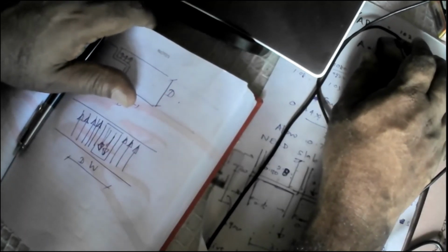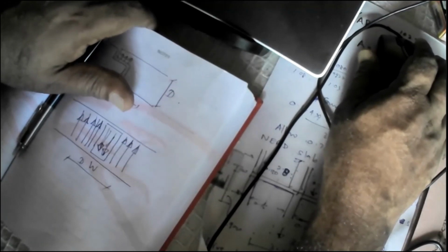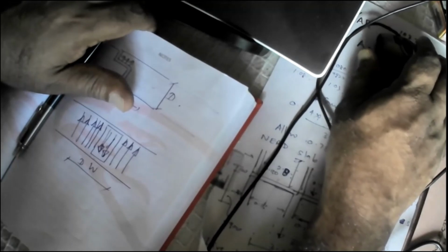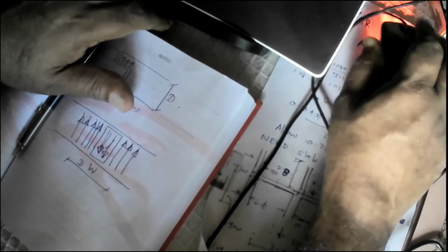So actually what happens is, when there's no distribution, this force becomes fairly small. And in such a situation, you don't get any bursting. Whereas if this force is concentrated, then there could be a possibility for bursting. So maybe the Indian code authors had some experience and went for this reinforcement. That is the explanation.